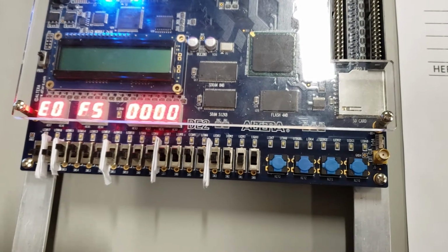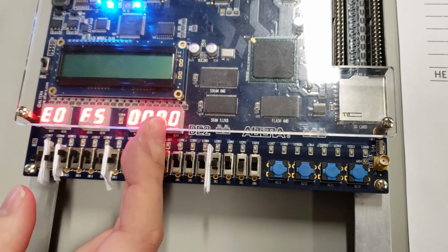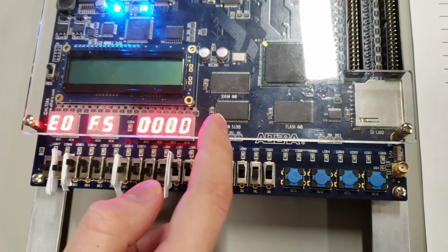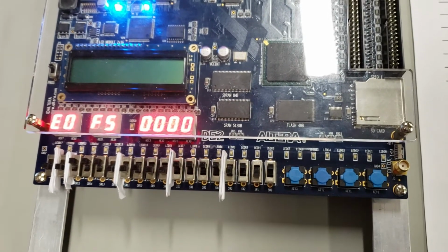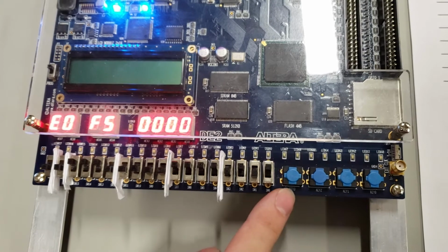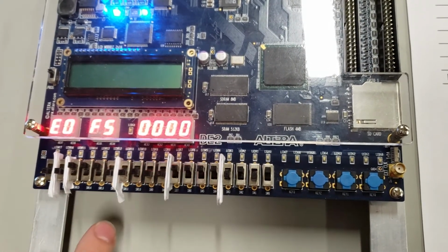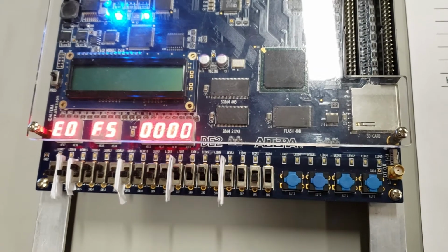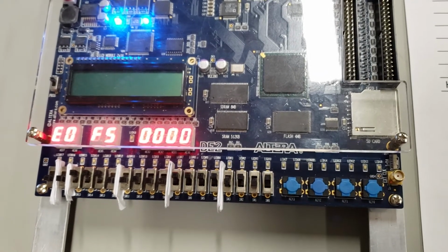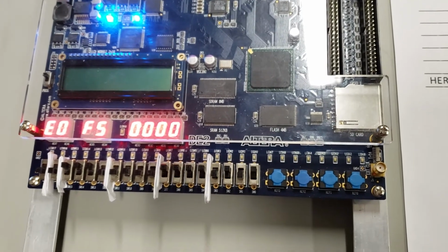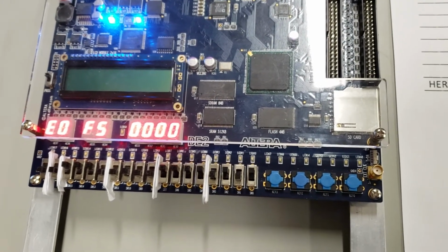Now, both registers are set up with the address and the data for that address. It is sitting at the doorstep of the SRAM chip on the FPGA board. Pressing in key 3 will then write this data to this address on the SRAM chip. There is no indication that the data was written, only that the button was pressed. So we must then move on to the next instruction.